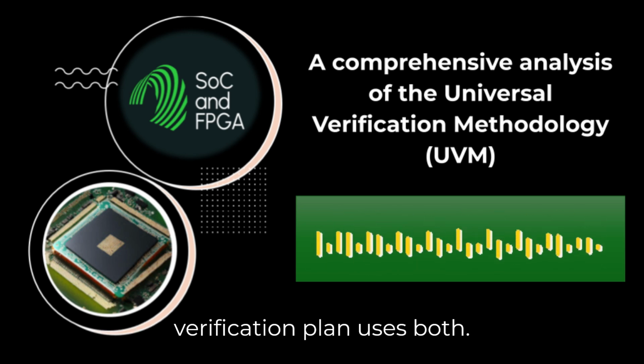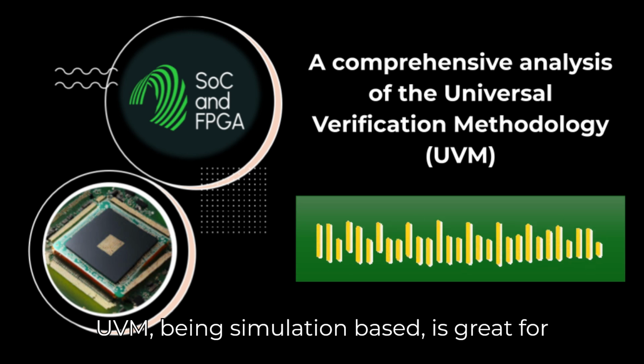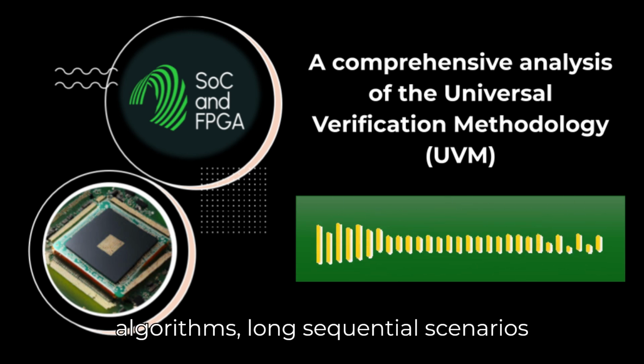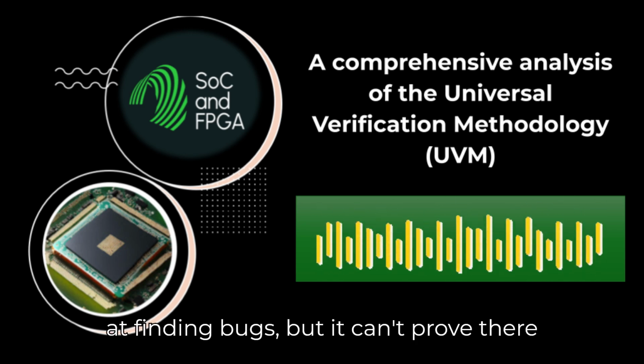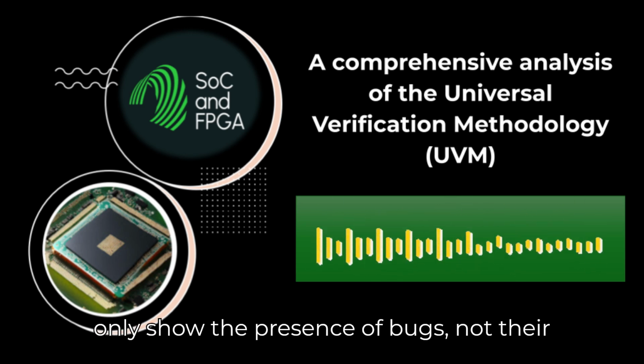A strong verification plan uses both. UVM, being simulation-based, is great for verifying complex data path logic algorithms, long sequential scenarios involving lots of state. It's excellent at finding bugs. But it can't prove there are no bugs. Right. Simulation can only show the presence of bugs, not their absence.